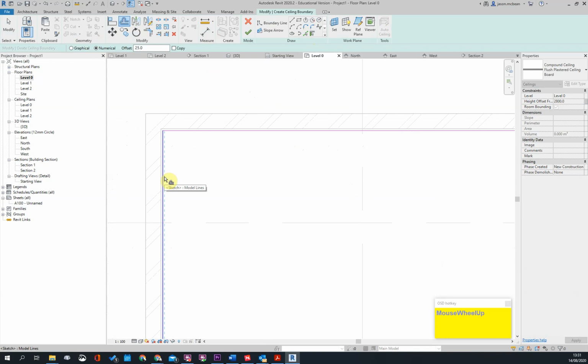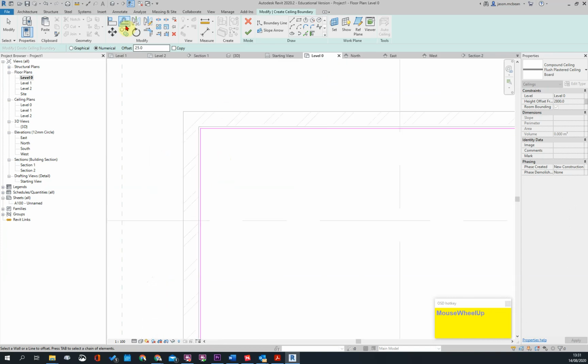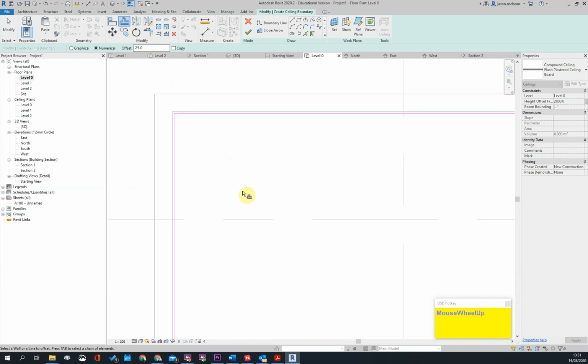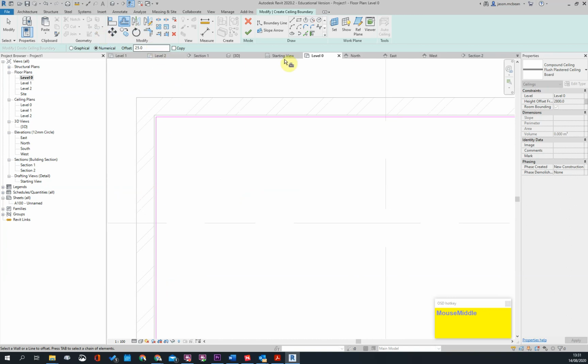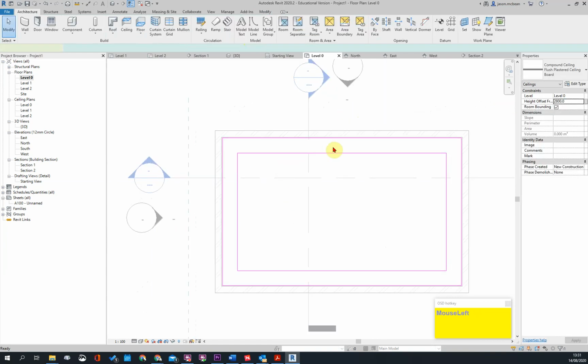A bulkhead is usually, it depends if you put lighting in or there's a ceiling tray. So your bulkhead either steps down or steps up. In commercial buildings where you've got shop fronts or glazing, your external side of the building is all glazed. You have a bulkhead that steps up, which I'll demonstrate now. And a bulkhead's usually, it varies, 500, so I'm just going to give it an offset of 500. So I'm going to say pick again, and offset 500. Tab, I just remember, pick line tool again, tab. Okay, so that's my flush plaster.